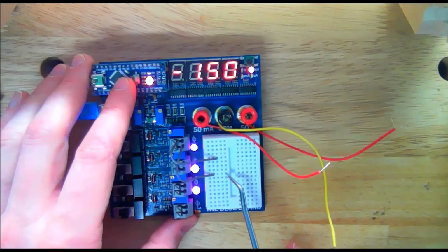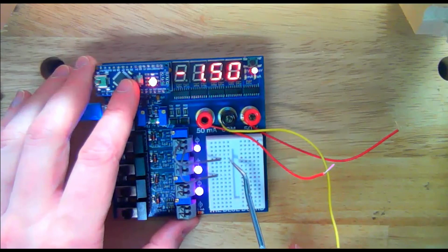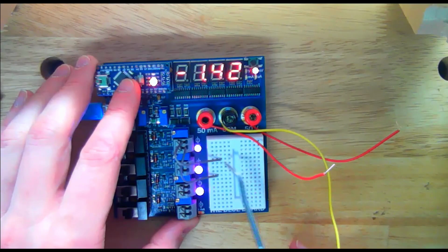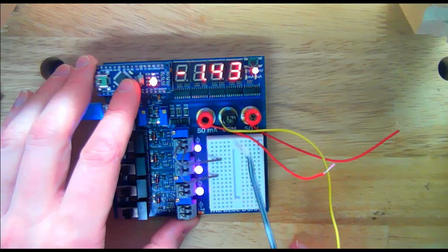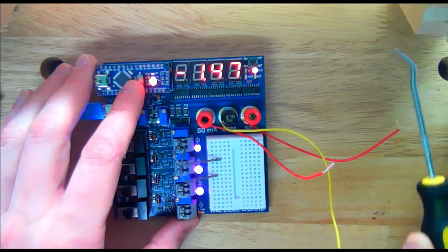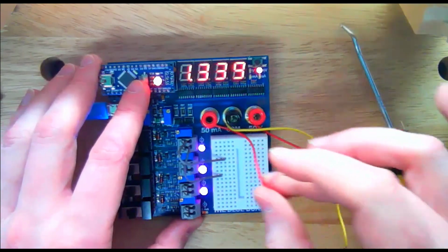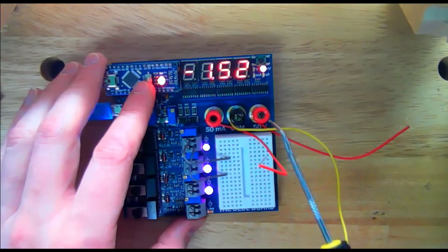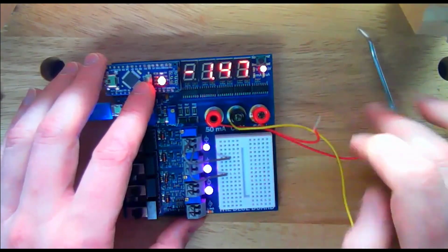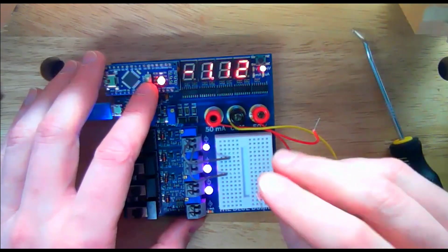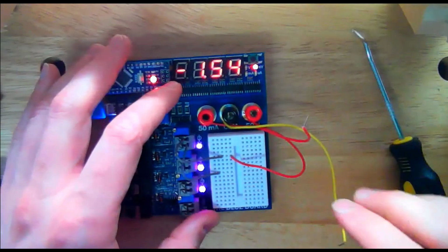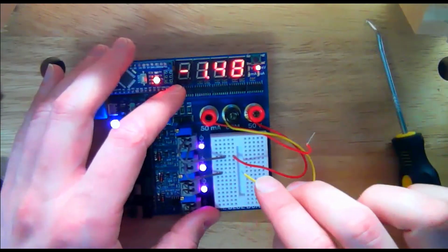So let's say we want to measure these supplies. Let's say we want to measure this 3-volt supply. If I connect the red voltage side of my voltage meter to this row, and I connect the common to this row, I should be able to measure the voltage across this. So let's do that. Oh, sorry, this is my current supply. This is my voltage supply here. So we have to connect the wire from the supply that says 50 volts. We will connect that to this top row, and the common wire we will connect to the bottom one.